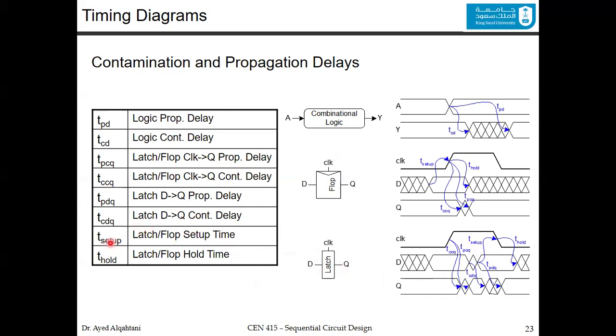We also have the setup and hold. The setup time or the hold time could be for the flip-flop or the latch. The setup time is measured from the critical moment, which is the rising edge. The timing from D up to the rising edge is called the setup. From the rising edge until D must stay stable is called the hold time, until you really save the value within the flip-flop.